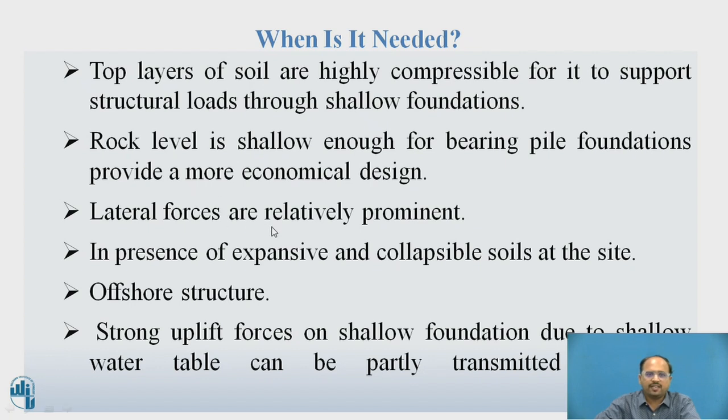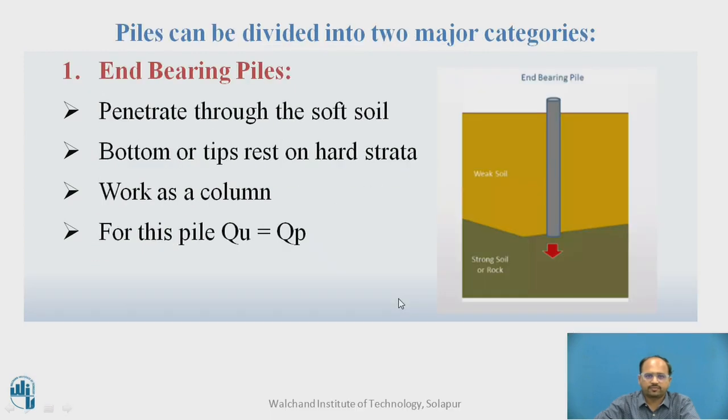Lateral forces are relatively prominent, or expansive and collapsible soil is present at the site. For offshore or onshore structures we can also use the pile foundation. Strong uplift forces on a shallow foundation due to a shallow water table can be partly transmitted to the piles.